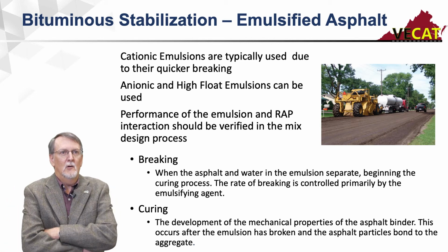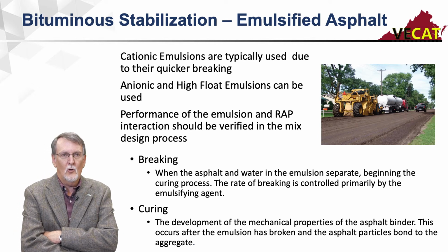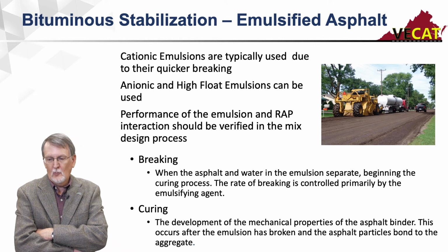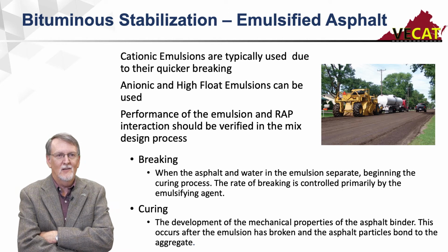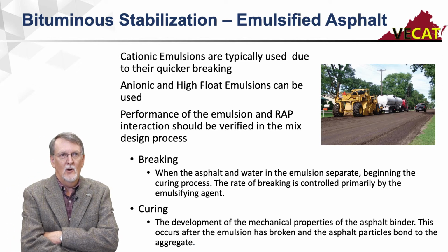But we want to run a mix design and make sure that our materials work well with our emulsion. And then there's two terms you'll hear sometimes. You'll talk about breaking and curing. So an asphalt emulsion starts to break when the water starts separating from the asphalt.